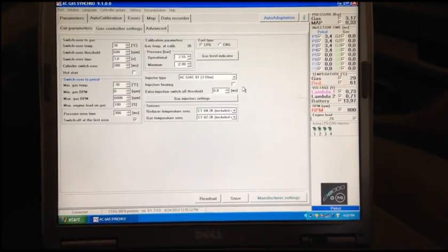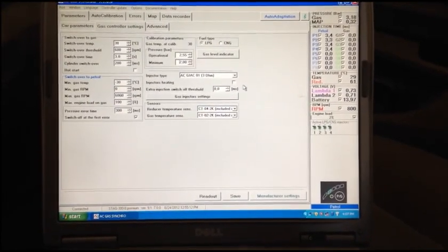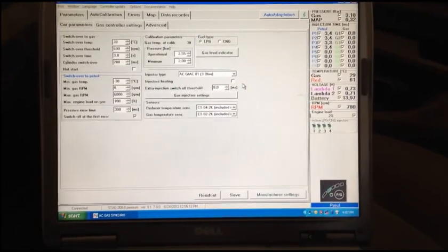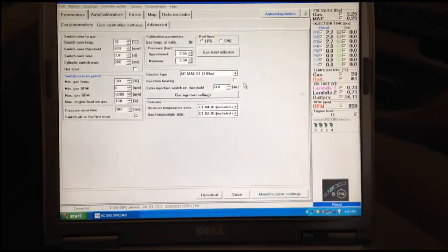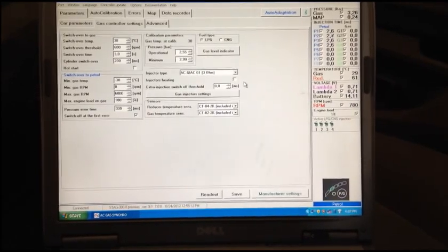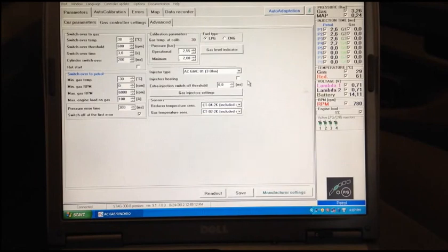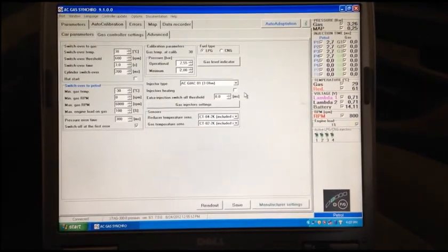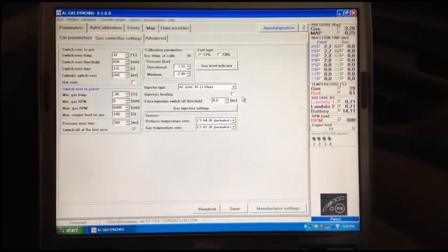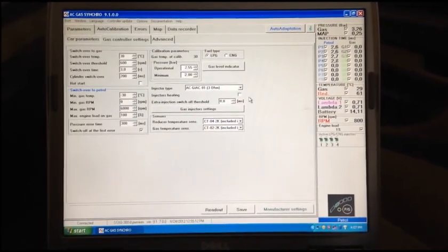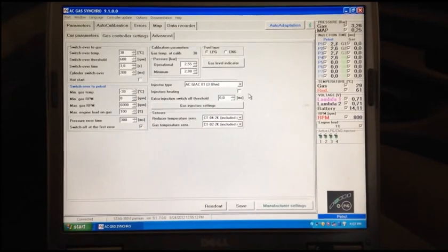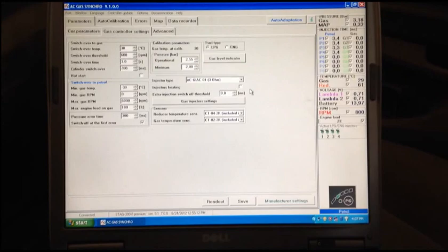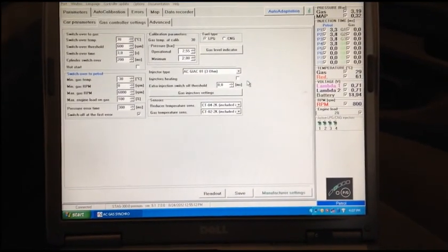It'll drive a little current to the coils, not enough for them to open up the injectors, but just enough to build a little heat around the solenoids for a certain period of time before it kicks in, to try to warm them up for you. I usually don't need that. Like I said, I'm not in a very cold climate where I'm at, so I don't usually have to engage that, because it also makes the switch over time a little bit longer because it's doing its thing there for 10-20 seconds trying to warm those up before it kicks in, so your delay is a little longer.